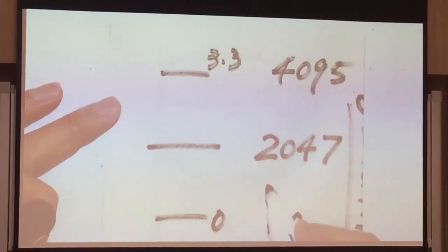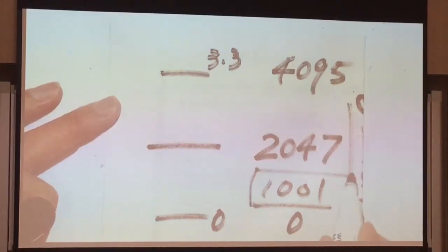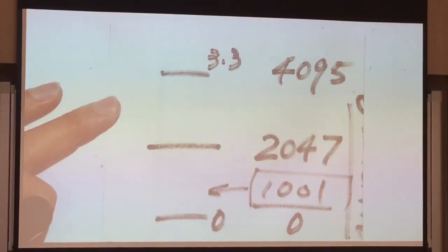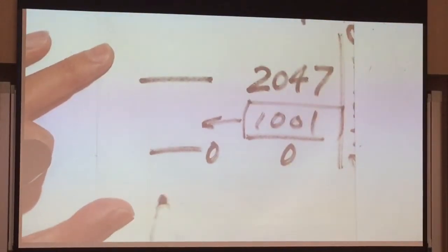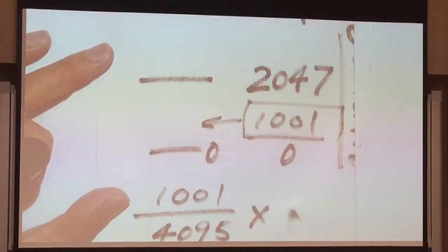Let's say you get a value 1001, just an example, as the reading from the analogRead function. What is the corresponding voltage level? You have to do a translation. Basically it's something like this: 1001 divided by your range, 4095, times 3.3 volts.